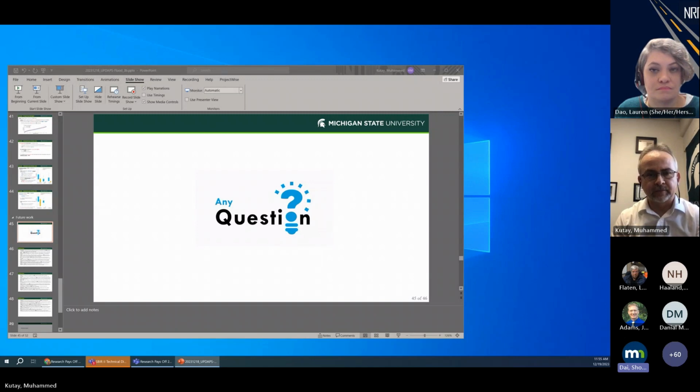Yeah, I agree with you. And the reason I'm thinking of this is, if the pavement is flooded and you have the strength criteria in the base, you can give guidance to the authority, say, during the flooding period, I can only allow certain vehicles to pass over the pavement, because if just one heavy load passes over the pavement, the whole pavement can fail. It's no fatigue type of failure anymore. So yeah, that's what I'm thinking.